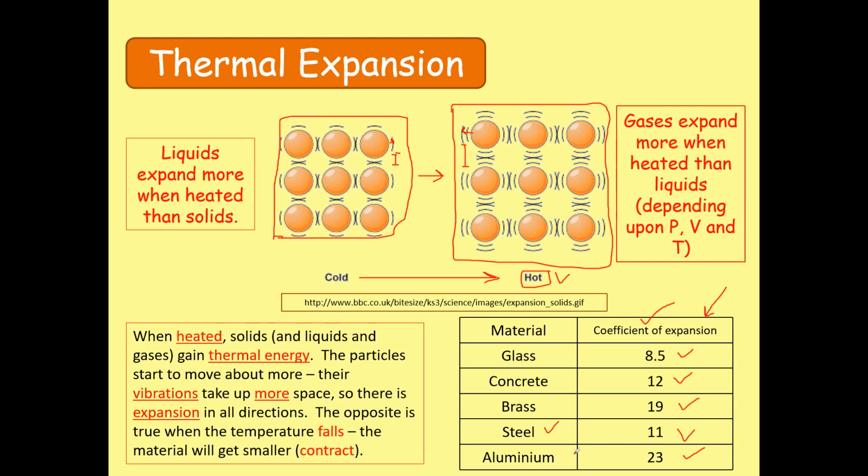But what if I make the key using aluminum? As soon as I insert this aluminum key into the lock, since the lock is at higher temperature, aluminum would start to expand, and that may cause the key to either get stuck in the lock, or it may not be able to operate the lock properly, because aluminum expands a lot more than steel. That means it is going to be harder for the key to operate the lock, right? It may not even operate the lock at all, right?